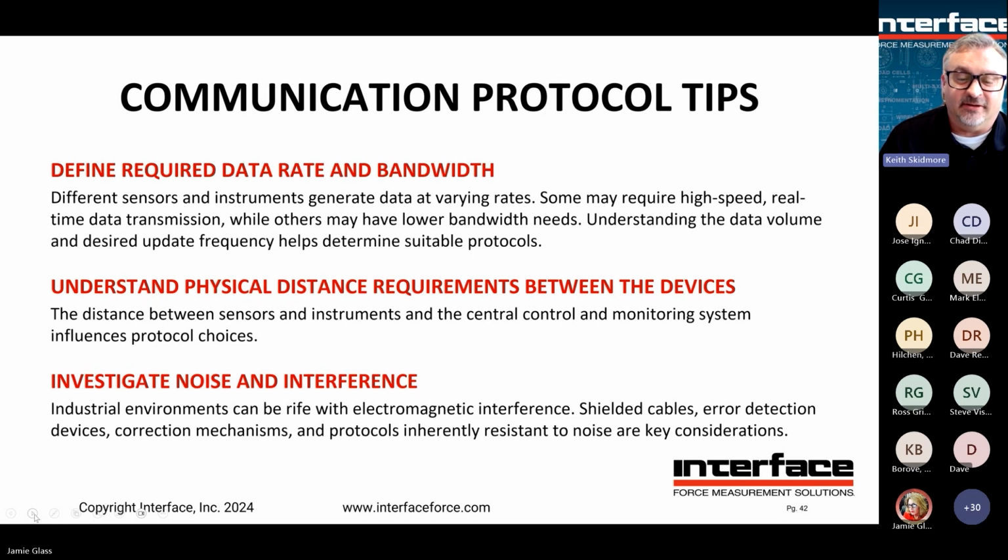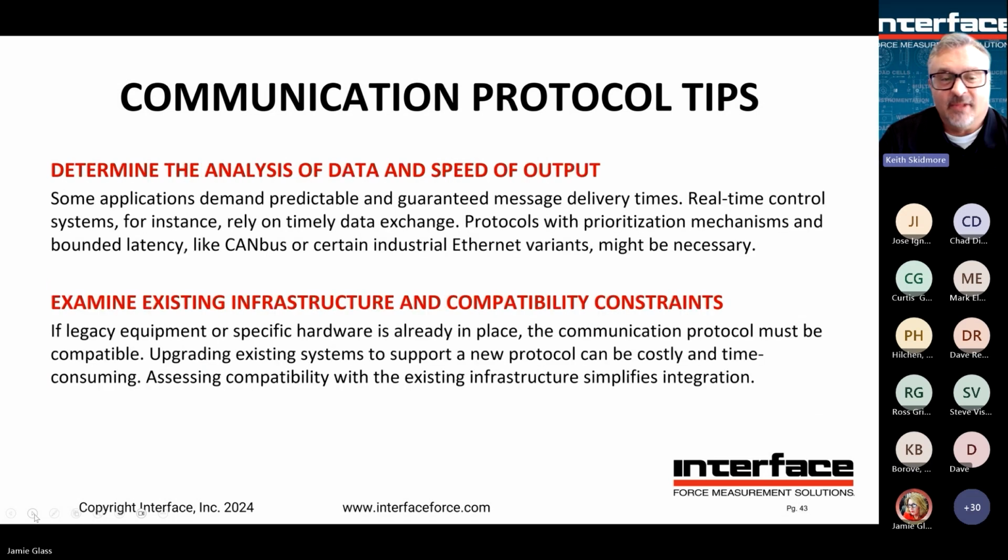The sensor is just the only thing in your network that is sensitive enough that it's obvious. So a lot of times it's really not a defect or a problem in the sensor. It's showing that there are serious noise problems that need to be addressed. And they might be having bandwidth problems too that you didn't realize, and the noise is affecting that as well. So tracking down the noise and mitigating it, or using protocols that are more inherently insensitive to it, may be in order.